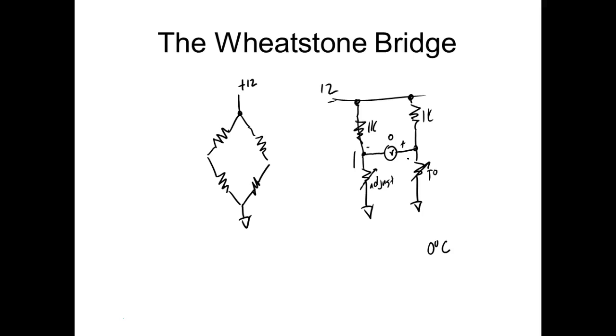Once you go about 3 times between full load and minus load, zero, you calibrate the scale. And that's what we used to do. And all we were doing was just adjusting the Wheatstone bridge. That's all we were doing, just turning those knobs.